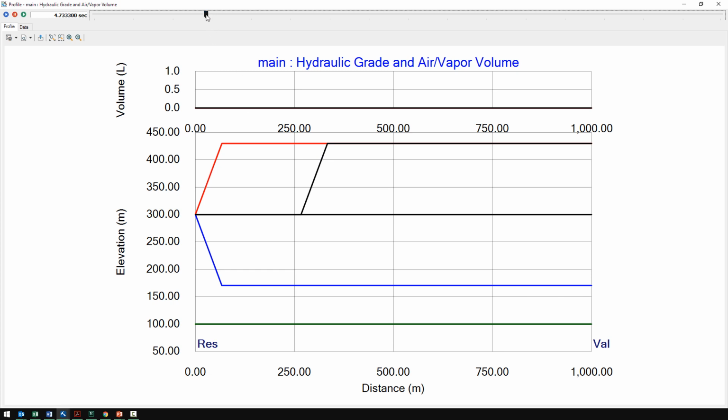So, and this can be very significant, because in some systems like this, where you have a valve closed, you basically have zero flow in this pipe during this process. Not quite zero. You have a small amount of movement of water at the endpoints because of the line packing that occurs from the molecules packing up against each other. But from that little bit of movement, with some friction incorporated, you can actually see this transient wave dissipate over time. But if I just kind of fast forward here, we can see it bounces back and forth, back and forth. It never decreases.